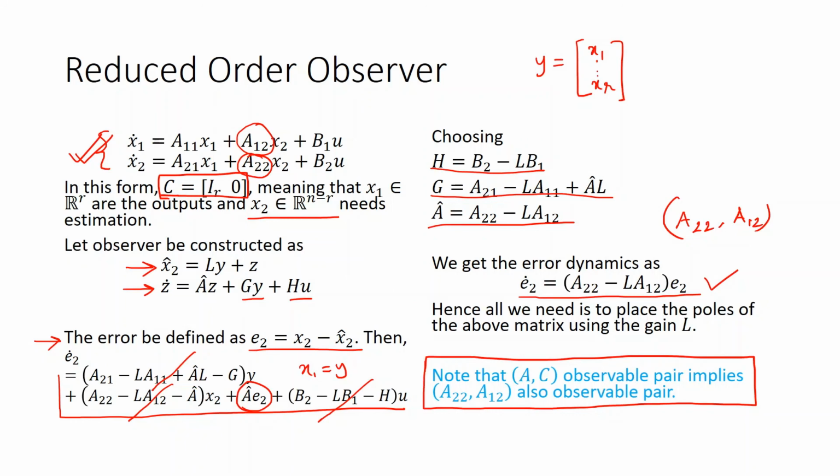place the poles, place the eigenvalues, in the left half plane. When can we do that? The idea of the dual system, and the idea of how we construct the observer as a copy of the original system with some injection term added, these ideas will remain almost the same even in advanced controllers and observers. So with that, I end the discussion.